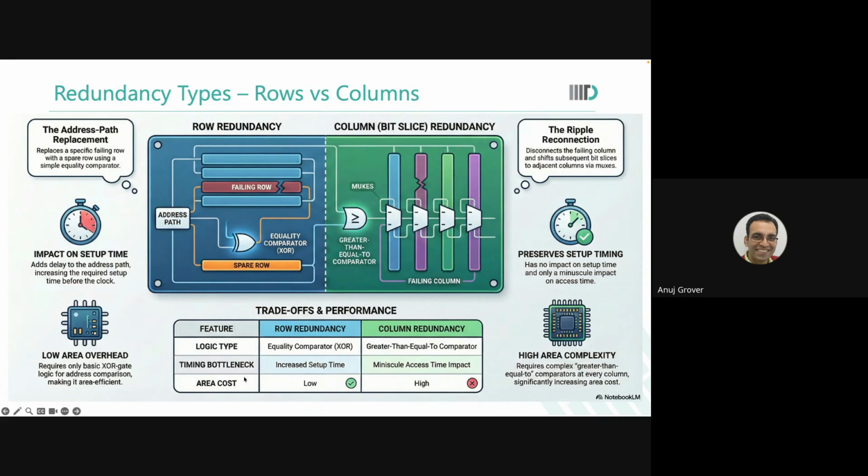So because of the one-sided flow of current, copper atoms will move. And where there was a 50 k ohm resistance, there were already very few copper atoms. This is the part that is getting heated up. So these few copper atoms now are more mobile and they will move. So what happens? Very soon you will have an open there. That is the rectification.